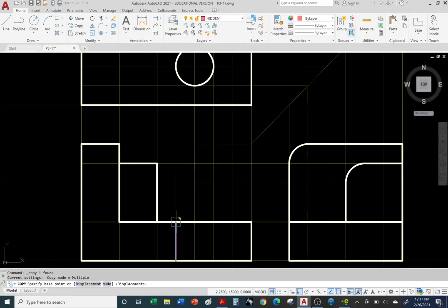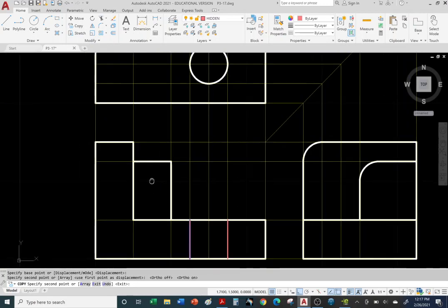There it is. Okay, and let me turn off ortho just so you can see. So obviously it's going to line up with the right quadrant of the hole, or the circular hole, right, in the top view. And we can click, but let me turn on ortho just to guarantee that it does line up correctly. As you can see, ortho only lets you go vertical or horizontal. And click. And by the way, you can keep on clicking. I'm just going to click for fun, some extra clicks.